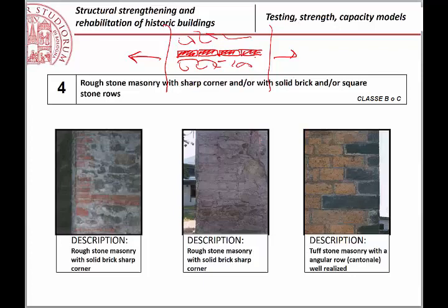Instead, if you put 2 layers, and of course there is some vertical loading over the masonry, where you have 2 blocks, I'm just separating them, because of the presence of the vertical loading, there is some friction between the bricks, and friction means the possibility of supporting some tractions in the transverse direction.